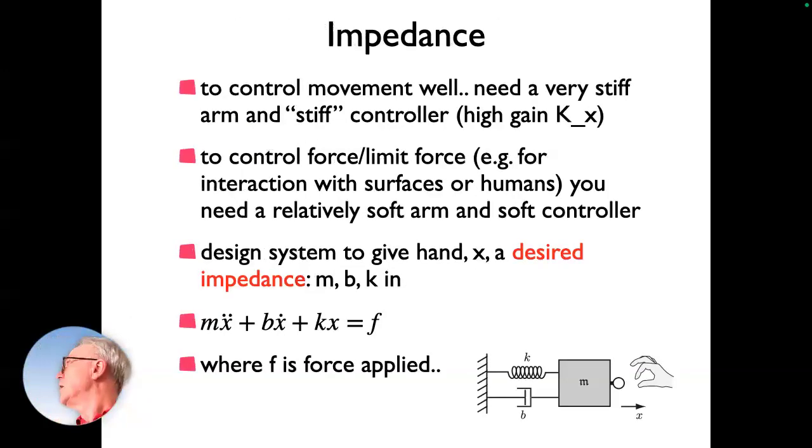So it's a somewhat formal way of thinking about that. For instance, if I think of this object as one I want to interact with, let's say this is the robot arm I'm interacting with, I want to give it a well-defined impedance. That is, I want the robot to resist me in a definable way. For instance, the robot approximates a damped mass-spring arrangement, and I want it to have a particular elasticity constant, a particular inertial constant, and a particular viscous damping.